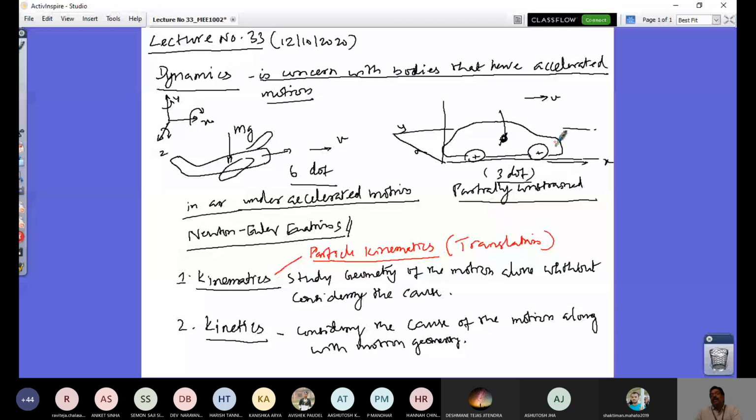So what is it that I have to do? I have to draw this tire wheel assembly separately, with its free body diagram. If it is on this floor and its CG goes along, there is a rotation of this, and you see here there is a tractive force and a resistance force called rolling resistance force. You'll see the load reaction here again, and the weight that comes on this. Like this, you draw the free body diagram and then you look at its motion. It is not only translation of the CG, there is also rotation. So I'll have to look at the rolling wheel.